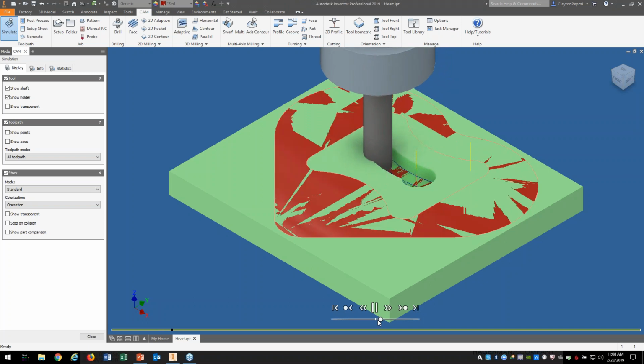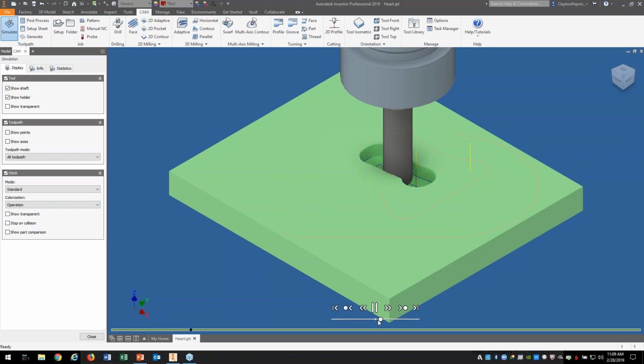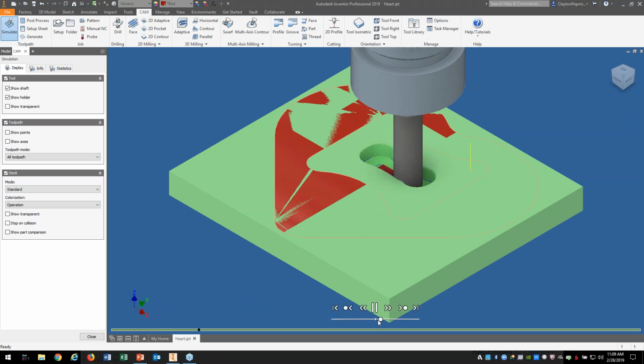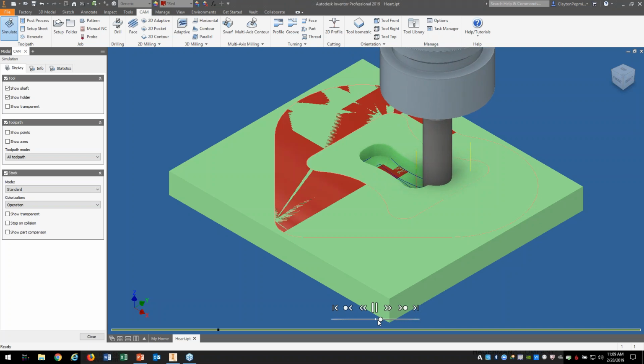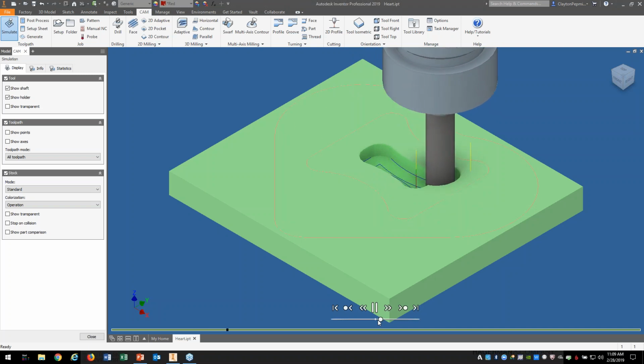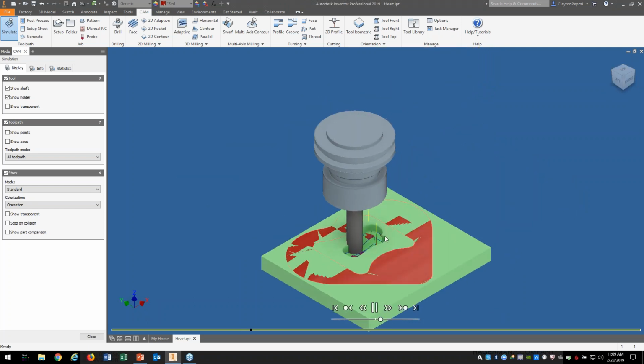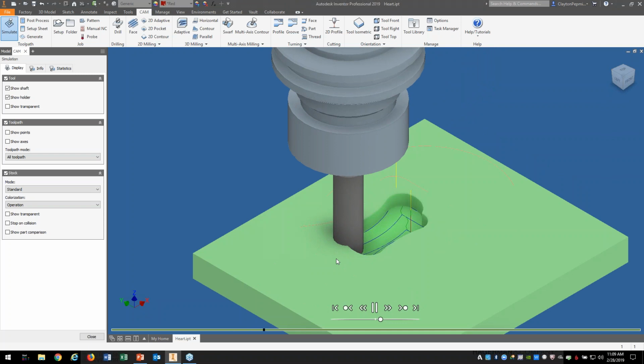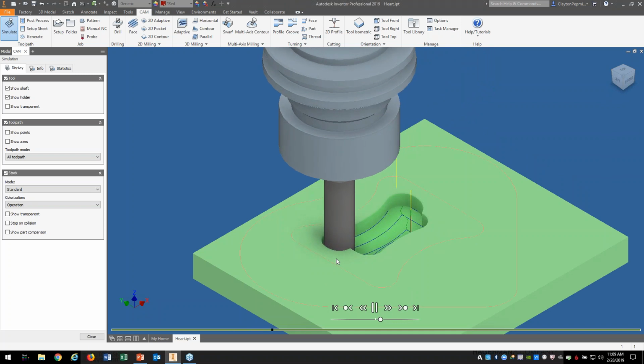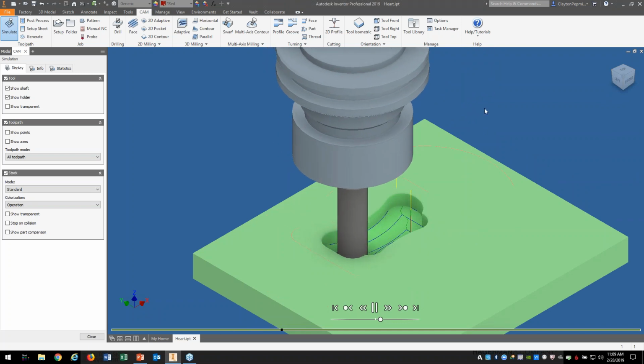You can kind of see it taking a full pass there. It comes across. Now it's only cutting a little bit. As we start approaching some of these corners, it's going to step over here shortly. Again, it's plunging the tool 100% there again. Right here, it's basically cutting 1/2 of the tool like I had specified. But as it gets into these corners, you notice you're really taking a deep plunge there.